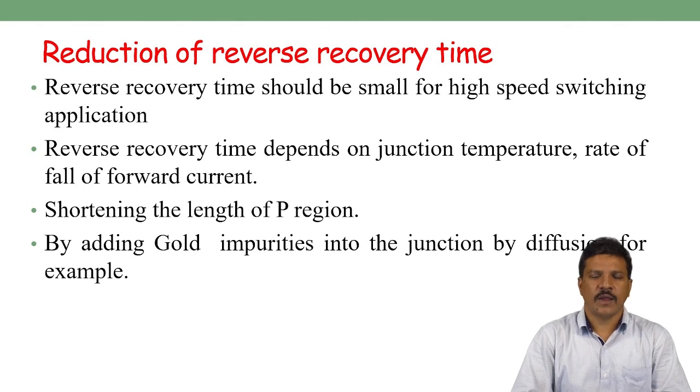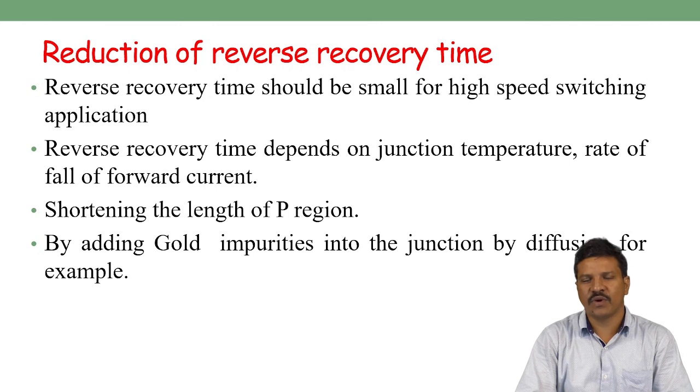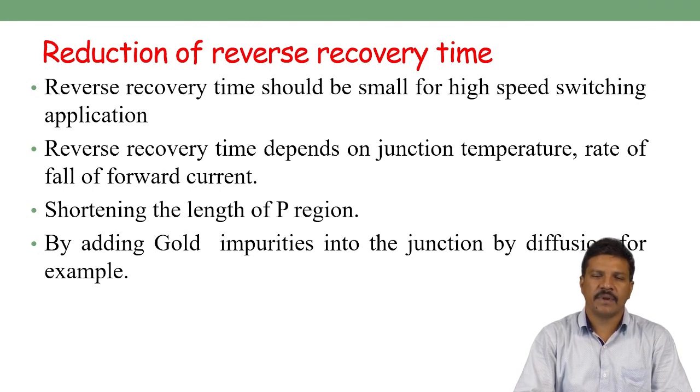we can conclude that a diode is simply switching from on state to off state and off state to on state, vice versa, within a fraction of time, but it takes time. That is represented by the diode switching characteristics. We can see the forward recovery time or forward state and reverse recovery time. So we can always focus on P-N junction diode manufacturing with the reverse recovery time reduced, so that we can use it in many high-speed applications. That is the most important thing.